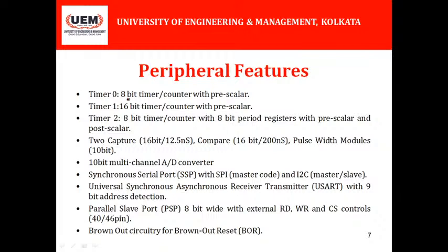I repeat, synchronous means both source and receiver are synchronized with a common clock. With SPI, the master mode, and with I2C, master or slave. So one port is acting as a master and another port is acting as a slave.